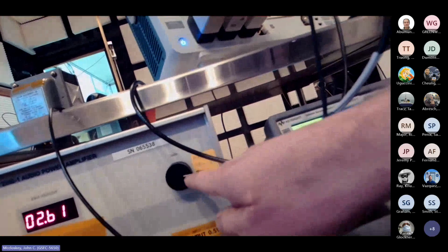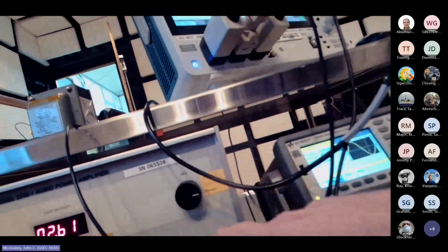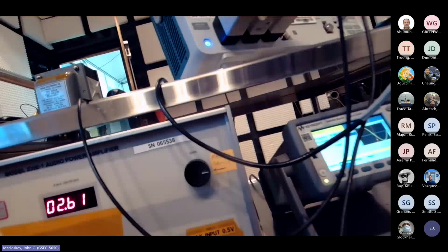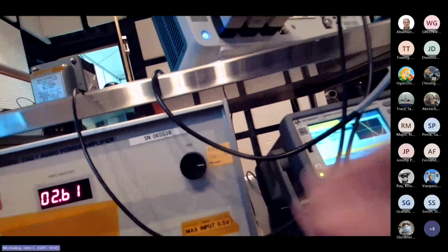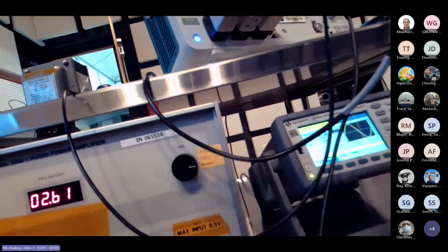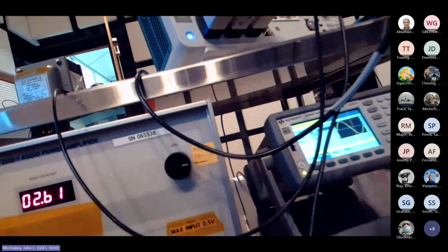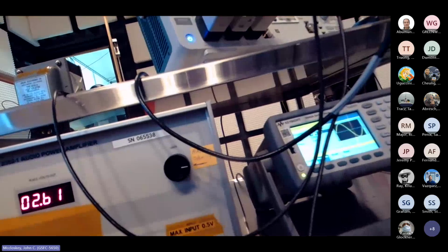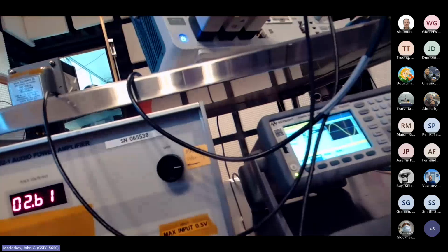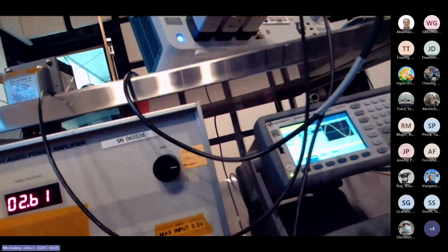So that's where I set the gain. I mean, you can set the gain to wherever you want it. It's pretty arbitrary, but once you set it, you leave it alone for the duration of your test. So I'm just setting it to that line. That's the default setting that we tend to use. So there we go. That's that for a 0 dBm input. That's the max setting you want to use. And as we'll see, we're actually going to be less than 0 dBm coming out of the signal generator.